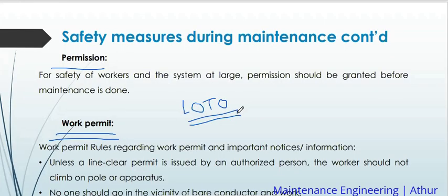This one we need to know. After isolating, even if it is a power substation, the guy goes on the panel that has switched off the feeder and puts a plate under maintenance. He puts a tag. For those who have ever gone into a substation and seen how they do switching, after the guy has switched off, he puts that tag that it is under maintenance.